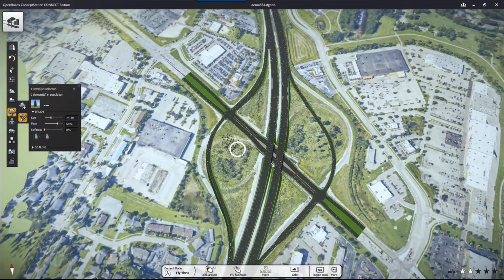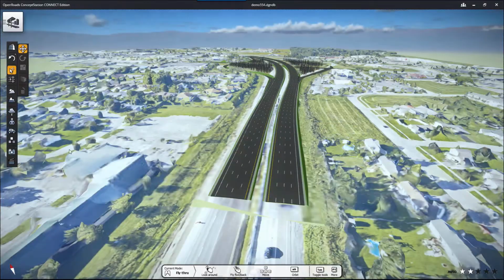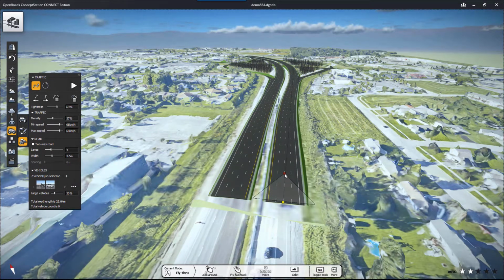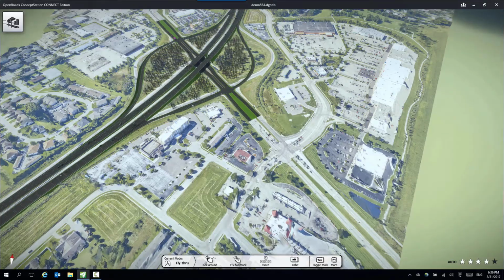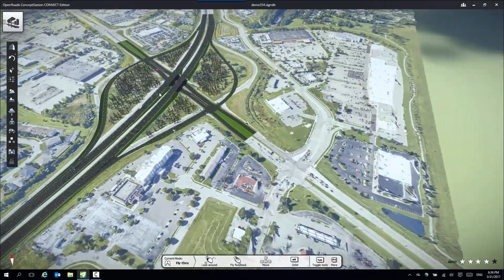Since the design work is done in 3D, we can quickly bring this into LumenRT. Here we're drawing in trees. Very quickly, just using a paintbrush, this is live. And then quickly lay out cars. Now this can be done on the MicroStation end. If you use the Vue simulator, you could put in your cars that way or come right into LumenRT and quickly lay them out.